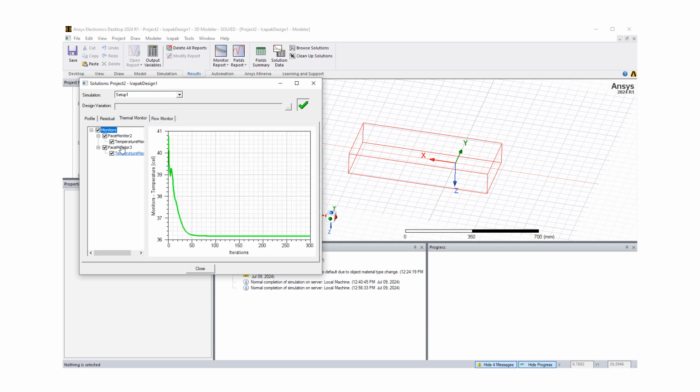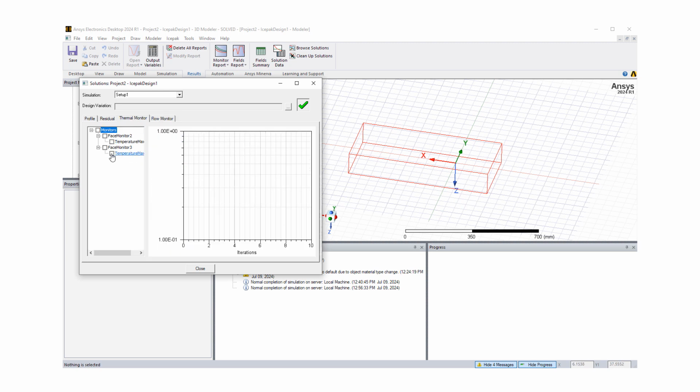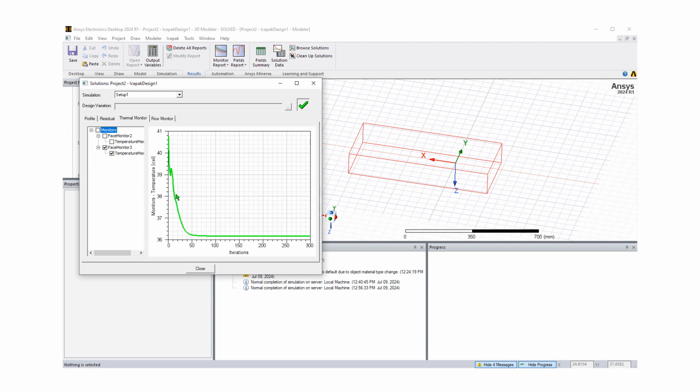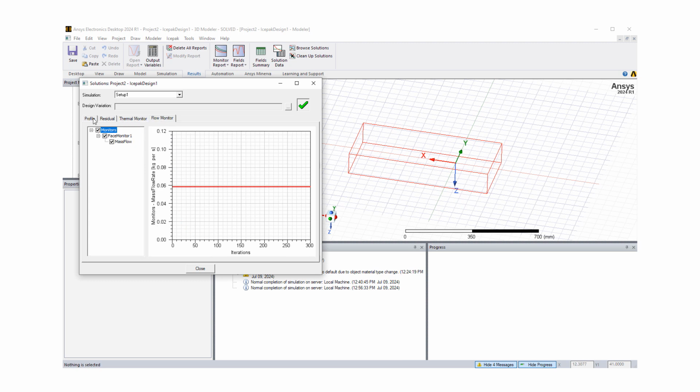We're going to look at the thermal results, and if we look at one of them, we start as high, and then it really converged, and the temperature also flattened out. So you can turn this off, see the other one, and it has the same temperature, which does make sense because we have a symmetric geometry with symmetric thermal loads. So it's all good news on this front, and this is the first thing you want to check after getting a solution.